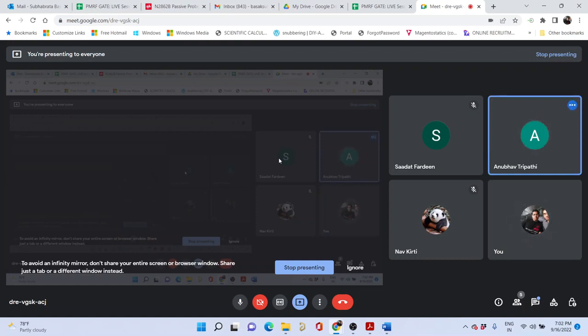Correct. When there is a pole on the right-hand side of the S plane, the final value theorem will not work. And what is the case with the initial value theorem? Is it applicable everywhere? In the last session, you told that we can apply that only for proper functions. Proper functions. Right. Now today you will see why it is so.